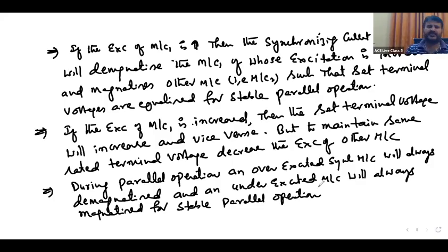This is a general statement. Overexcited machine will be demagnetized, underexcited magnetized. Who is doing this? Synchronizing power. Of course, that synchronizing power is itself reactive power.